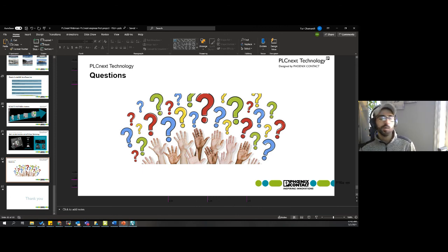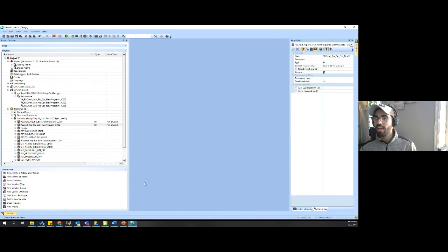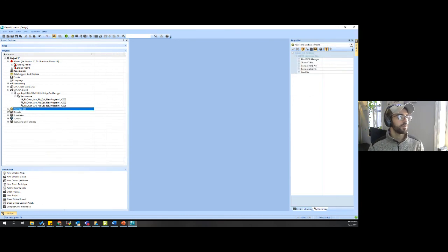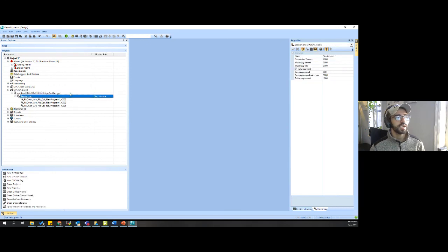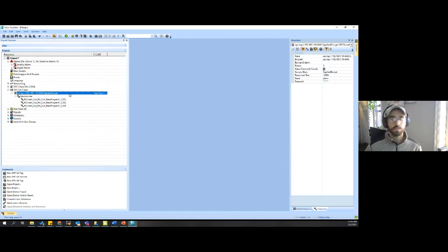In OPC UA, you don't need to do all that because OPC UA kind of breaks it down for you already. So when you look at the tag over here, and forget about the real-time DB, you're looking on the OPC UA client, right? So you have a client, you have a session for that client to that server, and your tags are coming from that server.